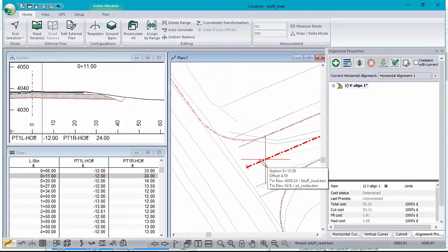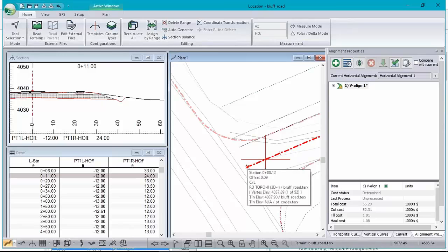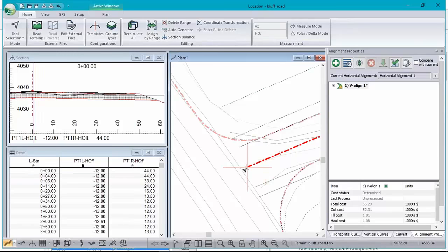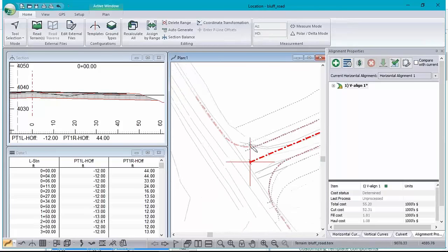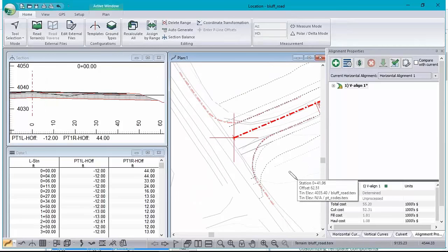And of course, on the other side, which I'm not going to do, we can only go a little ways because in this case, my cross section is actually going outwards from the road, and it doesn't even intersect with half of the fillet. The rest of the fillet over here is off the start of my alignment. So I can get that little piece in, and it will look okay up to station 0, and then it's missing.